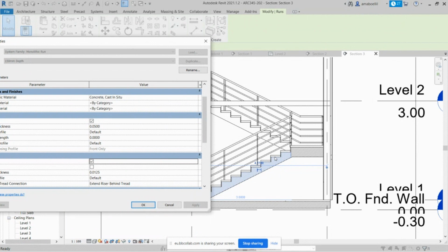They produce lots of friction between their foot and these threads, and over time it's going to be subjected to abrasion. You see that the stairs lose a portion of its material, and from time to time they need to be leveled up. So 4 centimeters is good to treat the surface and clean it up, and remove the uneven portion from time to time, so they stick to 4 centimeters.